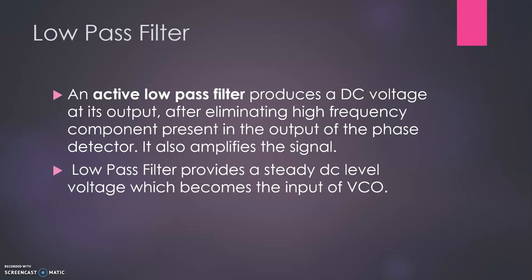Low pass filter. A low pass filter is basically used to remove high frequency components and noise from the output of the phase detector. The low pass filter provides a steady DC level voltage which becomes the input of the VCO.